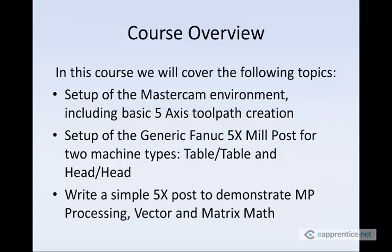We're actually going to set up that Fanuc post for both a table, a trunnion style machine, and a head style machine, a gantry machine. And then we're also going to write a simple 5-axis post from scratch, mainly just to demonstrate MP processing and the vector and matrix math that's available to you in the post processor. Really, the focus of the class is on using the generic Fanuc 5X mill post.